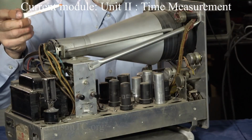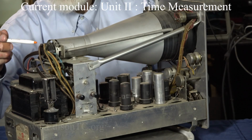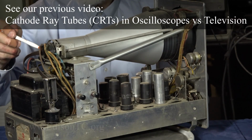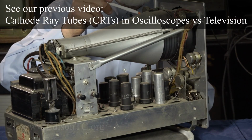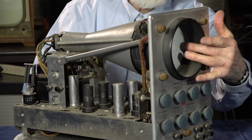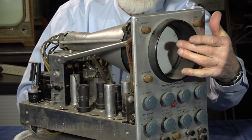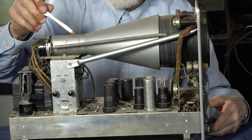The oscilloscope tube is made up of 3 major features. The first one is an electron gun on this end, and uses high voltage to accelerate electrons in a finely focused beam that hits this face. The second part is the face. It's covered with phosphor material. And the third part is a deflection system.